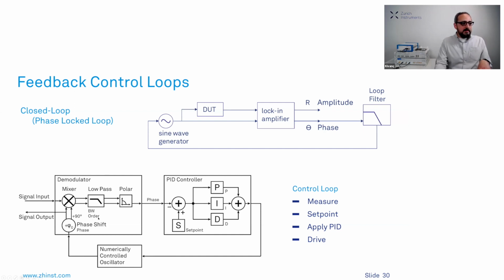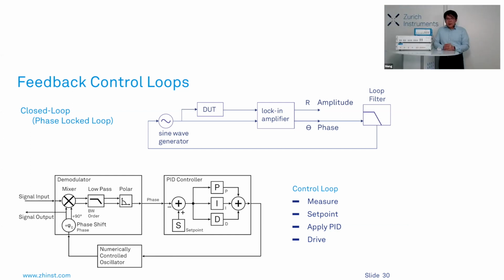And this low pass essentially has a time constant. So the narrower you have this band pass, the slower the measurement will be. But of course, this is always a balance. If you make it narrower and narrower, you have less and less noise on your measurement, but then it gets slower. So you need to balance in between. So this is the relation. Okay, I think this is a very good answer.